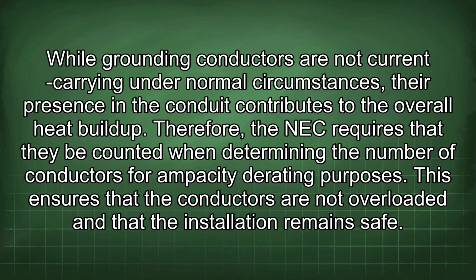While grounding conductors are not current-carrying under normal circumstances, their presence in the conduit contributes to the overall heat buildup. Therefore, the NEC requires that they be counted when determining the number of conductors for ampacity derating purposes. This ensures that the conductors are not overloaded and that the installation remains safe.